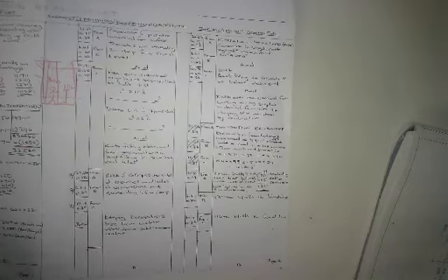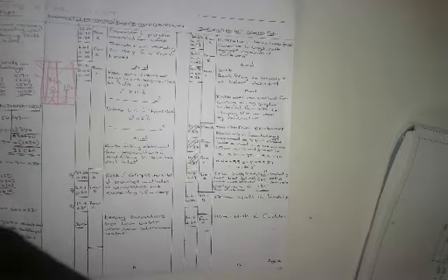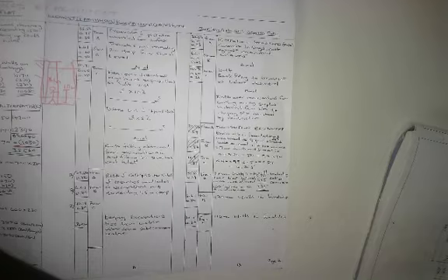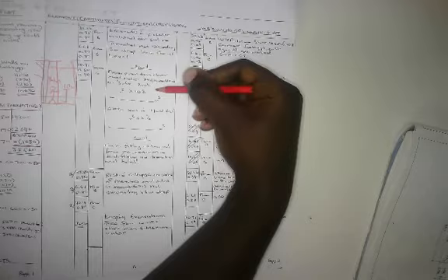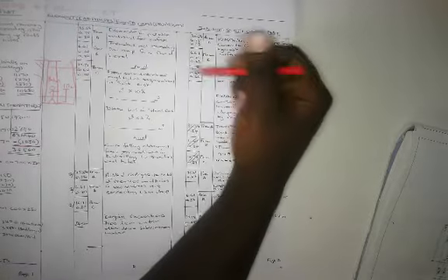As I was saying again, you need to describe to the contractor what they must do. So you must learn to practice doing descriptions. You're going to tell the contractor: excavate in pickable material for surface trenches not exceeding 2 meters deep from ground level, and extra over trenches and holes excavations in soft rock.